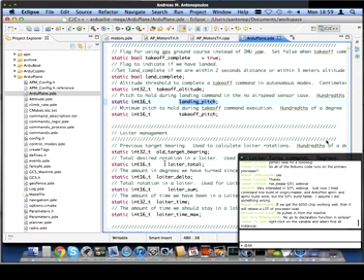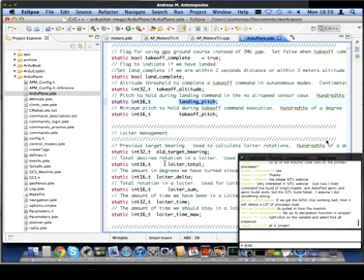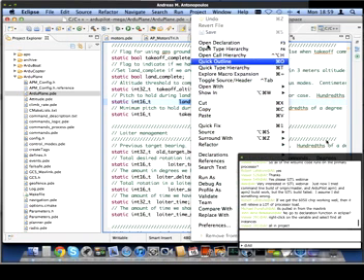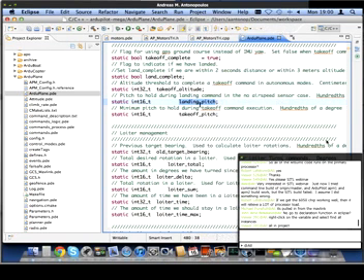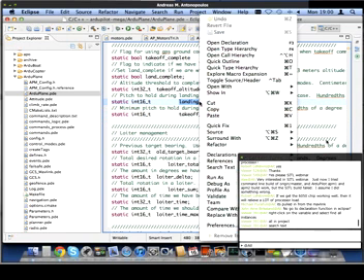Now, I think I know why that bug happened. That's probably because it was lost in the conversion from Mavlink 0.9 to Mavlink 1.0. I'm just checking in our code history to see whether there was any code removed that got rid of the setting of that landing pitch. So I'm just doing a quick search through the code history. Okay.